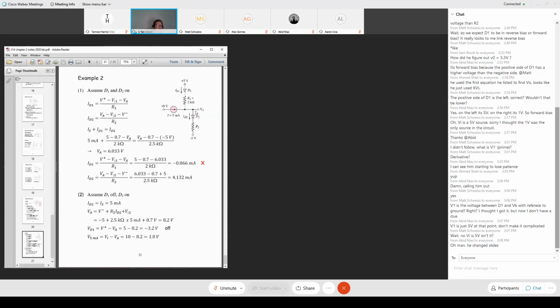I have this voltage VA, and this side minus V gamma 2, VA minus V gamma 2. I get this point. If I subtract this side voltage, V minus, and divide by the resistance R2, in theory I derive the equation to determine diode 2 current, ID2. Well, that's not all the story. You can say that's ID1. By the equation, I can calculate this. ID2 calculated by the second equation.